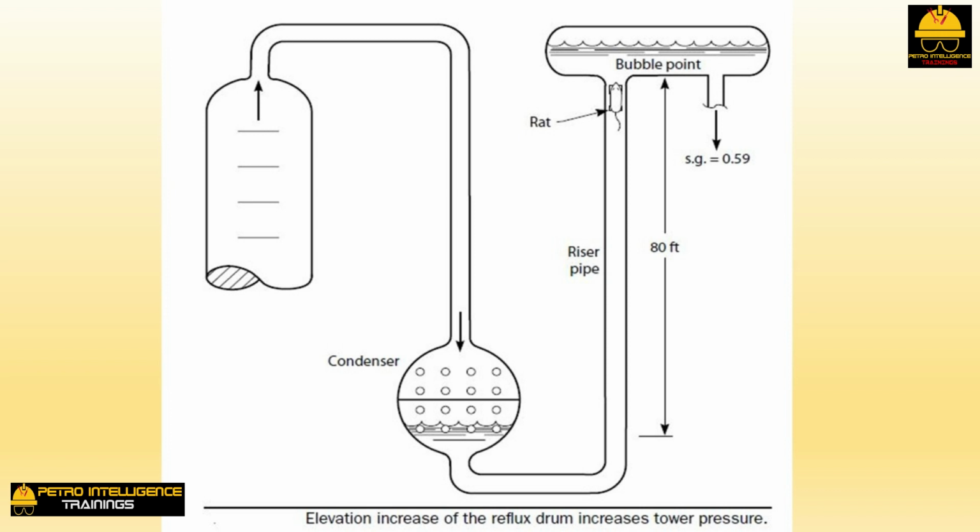The condensed butane now flowed across the rat. The rat died. Well, we all must come to that end eventually, although perhaps not quite that exact end. Such is the way of all flesh. This rat is called a 20-pound rat. Not that the rat weighed 20 pounds. The 20-pound refers to the pressure drop of 20 psi that the liquid encountered as it flowed across the rat's now lifeless body.